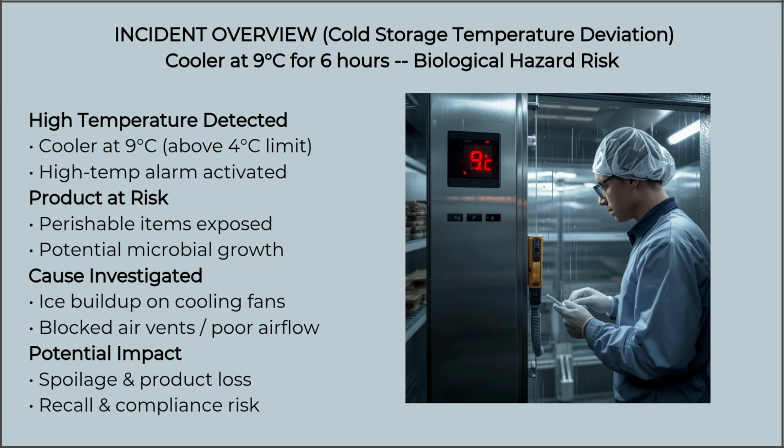Cause investigated. Maintenance inspection revealed ice buildup on cooling fans. Air vents were partially blocked, restricting airflow. Condenser performance was reduced due to overdue preventive maintenance.